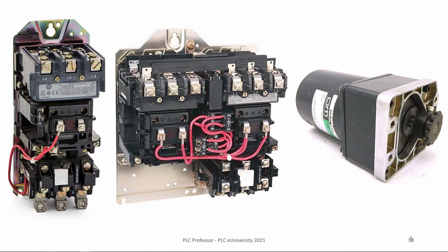So you see one of those, and then right next to it, you see the upper part of it, the actual switching part of it, minus the motor overloads, because you only need one motor overload relay for this one motor. So you have power coming in the top and going out the bottom. So you have two L1, L2, and L3s, and then you just have one T1, T2, and T3 coming out of the bottom. The motor starter to the far left is just on and off for that motor.